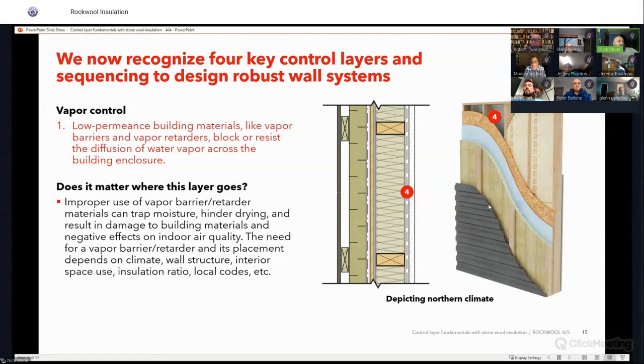And then as it gets moisture inside the cavity, it signals for the cells to open up and dry that system out to the inside through the material, getting that moisture out. And then once it's gotten out of the system and it becomes drier again in the cavity, it's going to close those cells back up. So that ability to have that kind of swing within those interior smart membranes is super important for our designs now because of that cooling load that we're adding into these buildings.